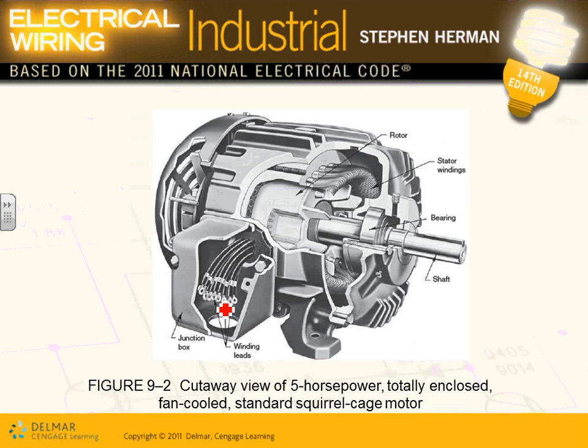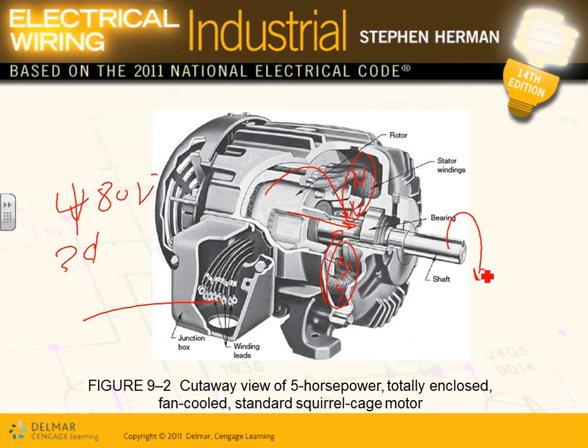So that's kind of the magic about it. Right from here, Karen, you bring the voltage. Here's my three-phase 480 volt. You bring it in here. Then you create a magnetic field. You induce voltage into the rotor. The induced voltage will create induced current. The induced current will create north and south. And you have also on the stator north and south. And these two poles will start pulling away from each other. Same thing. And this will give you rotation into the rotor or the shaft.